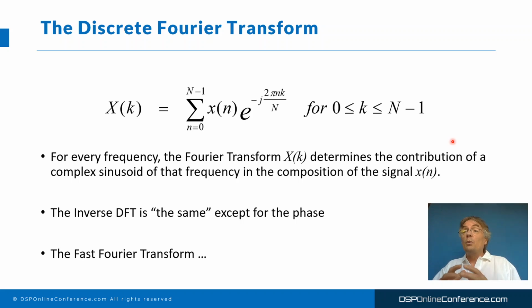We acquire an array of data in the time domain of big N samples. We then perform the DFT or FFT operation to get that sequence from the time domain to the frequency domain. And it's all processed as a block of data, so it's not a streaming application like the FIR filter.